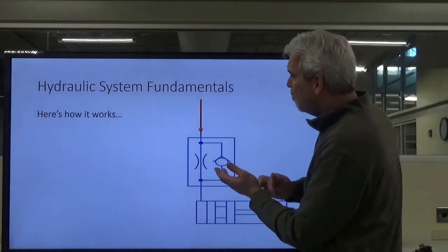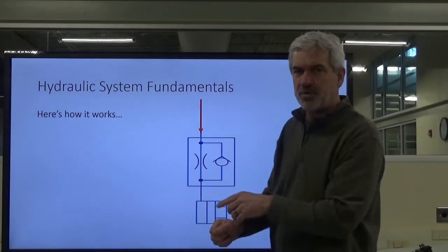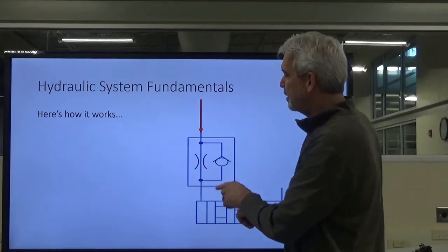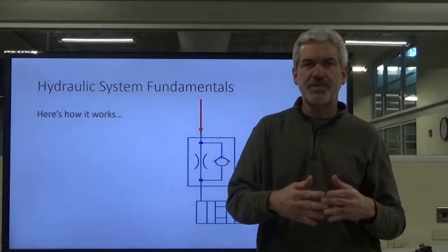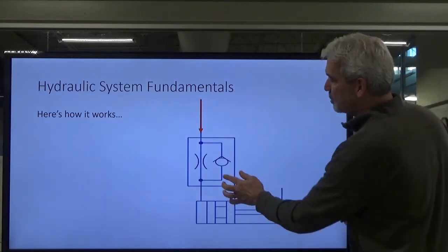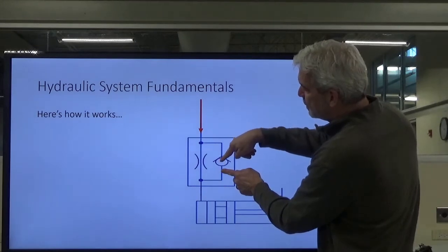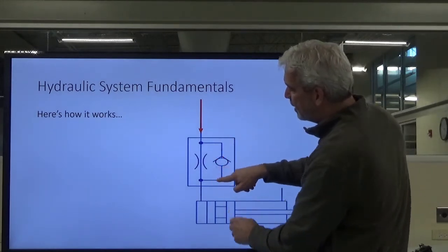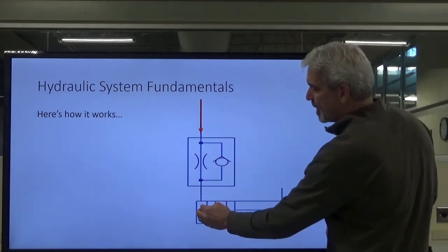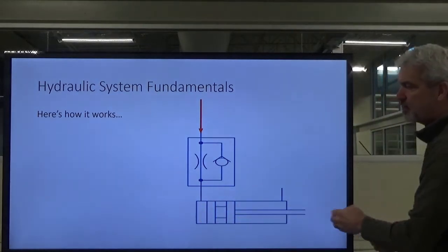But we got oil flowing through here, and we're kind of restricted here. We've got some that allow it to flow, but it's kind of restricted. So the oil is naturally going to look for its path of least resistance. So it's going to want to go through here. And remember, we said they've got a little spring back here, just a little one, and the oil will pull this ball off its seat, flow around it, and then it will come back on the cap side of the piston on this cylinder, and it will extend the cylinder, okay?